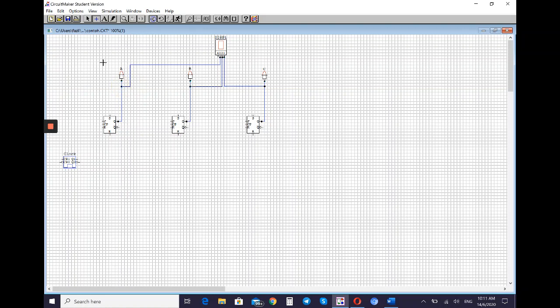Next we will connect the CP, which is the clock, on each flip-flop. The first CP is connected with your clock. Your clock has two outputs, Q1 and Q2, so you must connect to Q1. The same goes for the CP for B, also connected with the same line.